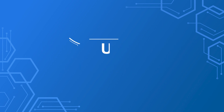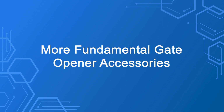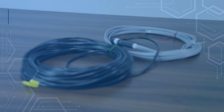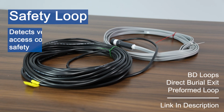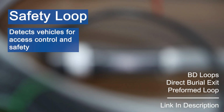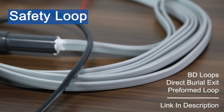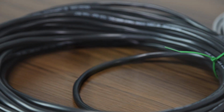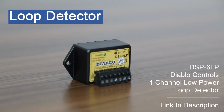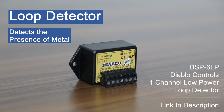Now that we've gone over UL325 compliant safety devices, let's take a look at other fundamental gate opener accessories, starting with vehicle detection. A safety loop is used to detect the presence of a vehicle. It is typically used to allow the gate to open when a vehicle approaches it, but also doubles as a safety device that can prevent the gate from closing on a vehicle in its path. It is installed into the ground in a loop formation that leads back to a loop detector.